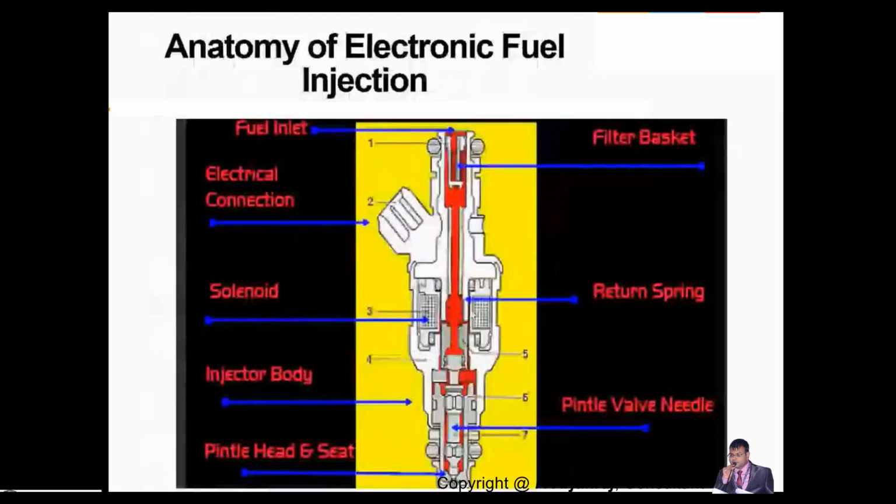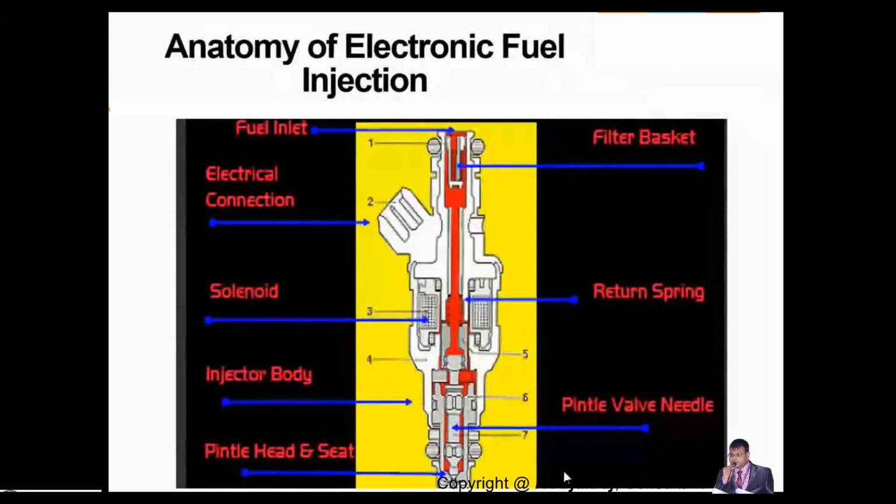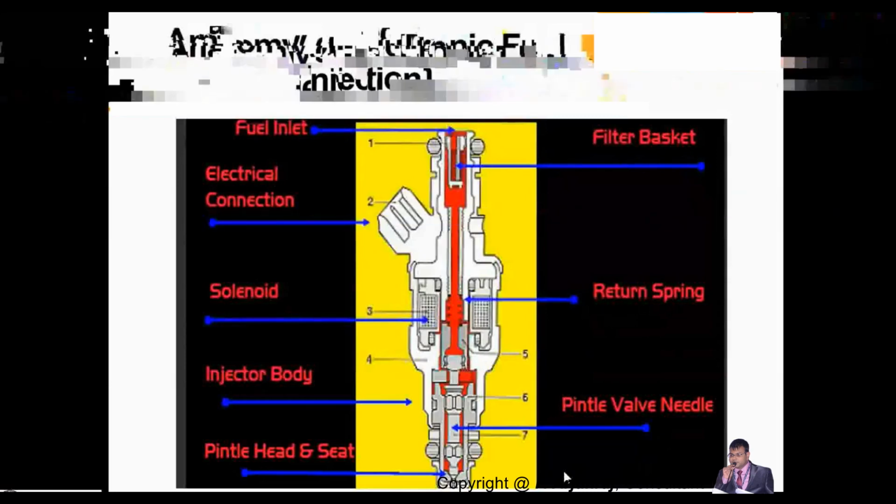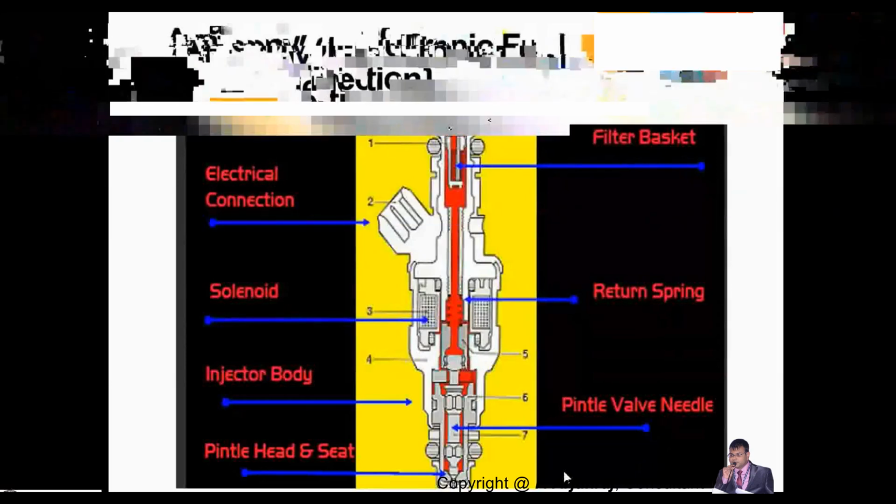Based on the force, the spring gets actuated, and it pushes the fuel from the inlet into the injection system, where it will inject the fuel with respect to the engine feedback coming from the ECU. Depending upon the engine RPM, the quantity of fuel gets varied. So the higher the RPM, the higher the quantity, and accordingly the spring